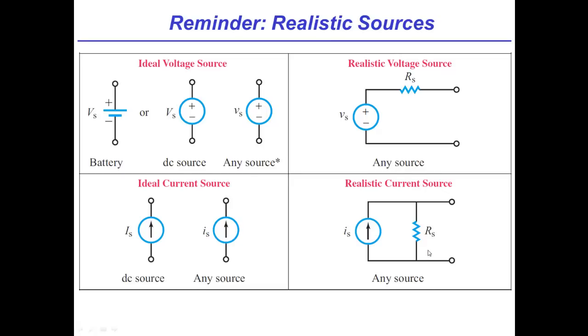Okay, so what you're saying in the bottom case is that that resistor RS is modeling the fact that not all the current from that IS source gets out to whatever the source is driving. Some of it is lost by whatever method into heat within the system itself. That's exactly right. That makes sense. Okay, and that's RS. Yeah. Okay, works for me.